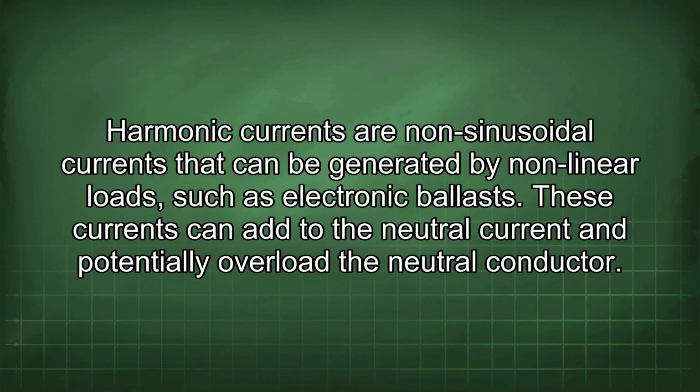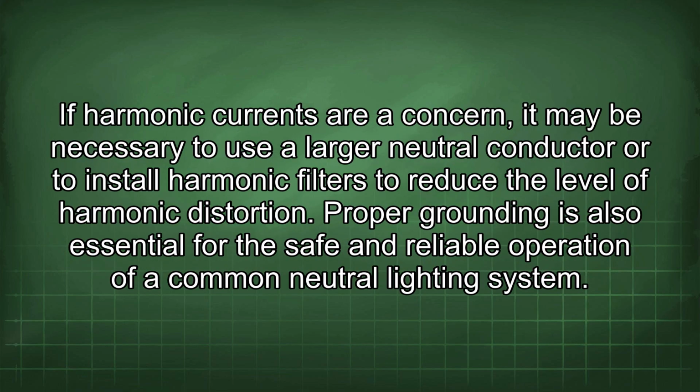Harmonic currents are non-sinusoidal currents that can be generated by nonlinear loads such as electronic ballasts. These currents can add to the neutral current and potentially overload the neutral conductor. If harmonic currents are a concern, it may be necessary to use a larger neutral conductor or to install harmonic filters to reduce the level of harmonic distortion.